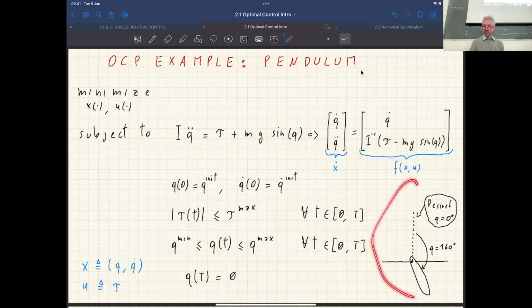If this system here is nonlinear, you can imagine that all robotic systems are nonlinear, because you cannot go simpler than that. Can you repeat why there is identity? It's not identity, it's the inertia. This is a scalar, not a matrix. Everything here is scalar because it's a 1 degree of freedom system.